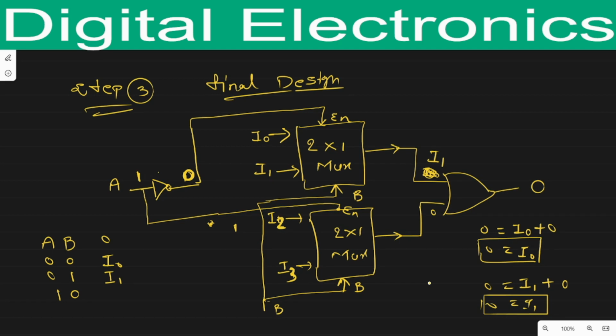Now when B equals 0, it will activate this I2, and this I2 will be transmitted toward this side. So here we will get I2, and from the upper we will get 0. So what is the output in the third case? The output will be 0 plus I2, so O equals I2.